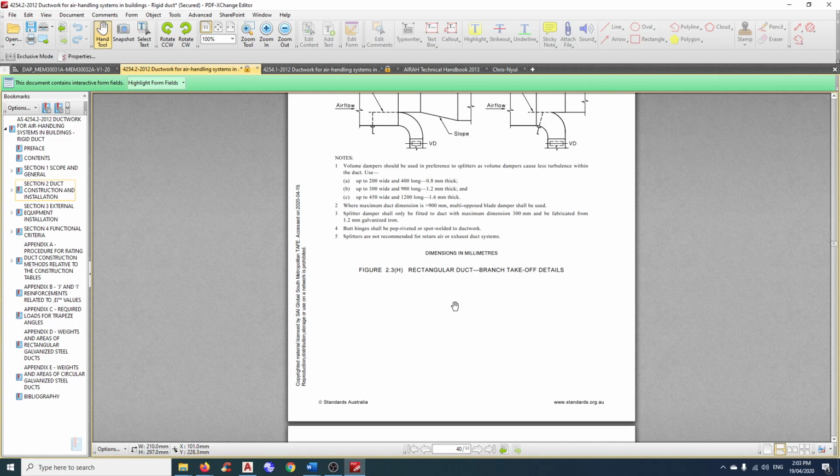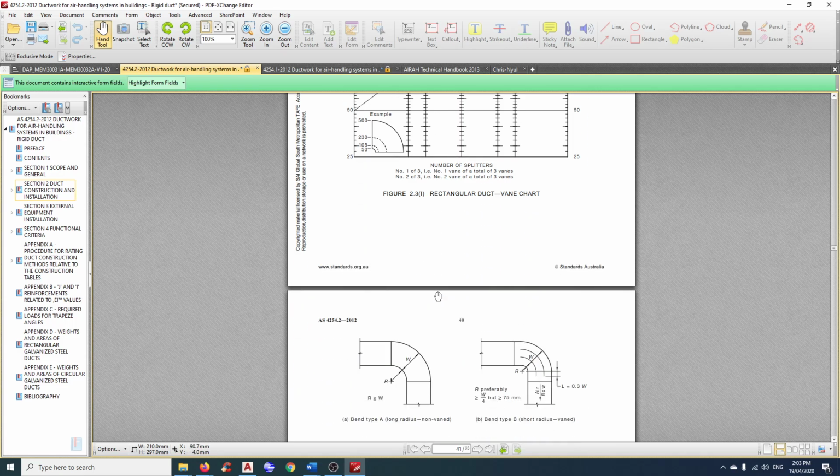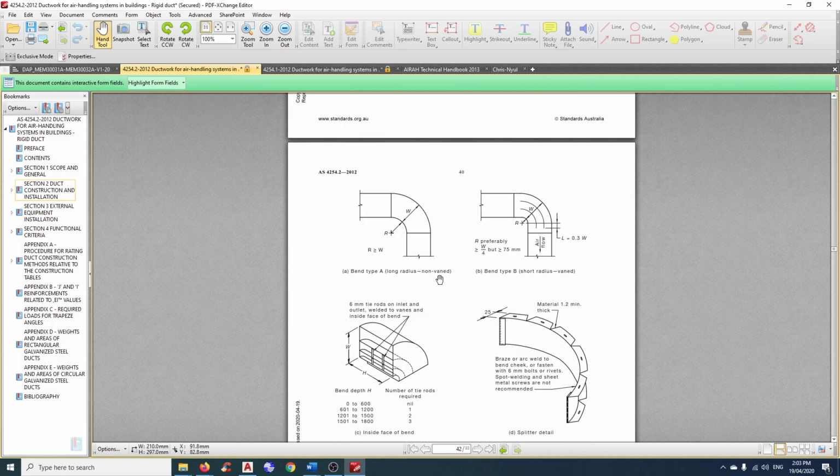For the purpose of shop drawing, really, you can draw the duct any shape you like. I do have one project that the duct probably looks like a triangle duct, which is very uncommon. It can be done. The reason is that the ceiling space is very limited, so the duct has to be similar shape of the roof truss.